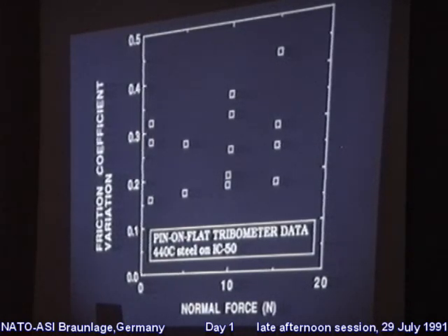Unfortunately, I couldn't measure any track widths on the friction microprobe. There was barely any evidence that anything had happened to the specimen. You could look at the tip of the slider and see maybe a little darkening, no pronounced grooving. You could look at the surface of the flat specimen, and if you were lucky, you may see a very small thin scratch, but usually you couldn't find it. On the other higher load machines, you see what is typical of what they call severe metallic wear, with a great deal of ductile tearing and significant plastic deformation.